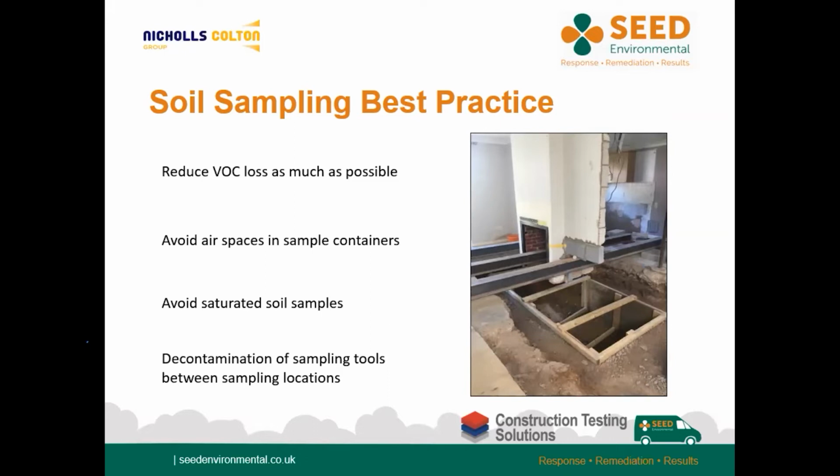Avoid soil samples that have been collected from within a resting groundwater body. The laboratory results could be more representative of groundwater quality than your soil sample. Stormwaters should also be removed from excavations prior to sampling as well. Sampling equipment, as mentioned earlier, also needs to be decontaminated between sampling locations to prevent contaminant carryover. Dependent on your suspected or known range of contaminants, this can be carried out with water or a surfactant solution.